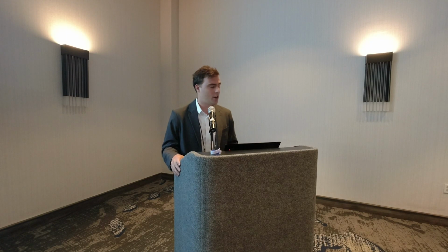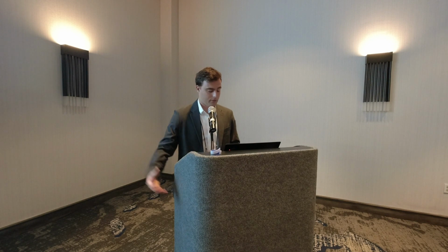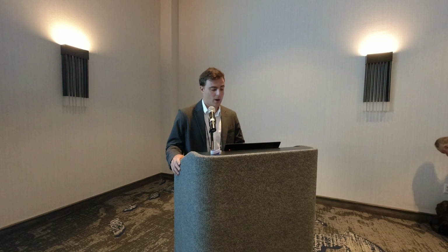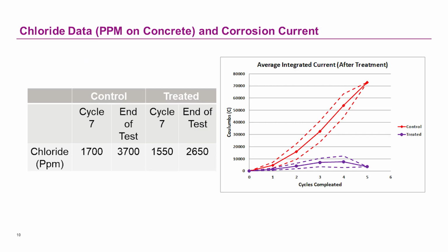And then the test is continued the same way, 2 weeks on, 2 weeks off of the chloride solution, and you continue to measure the chloride data. As you can see on the control, there's nothing stopping the chlorides from penetrating, so they continue to aggressively get higher in concentration towards the rebar. It's not on here, but this depth is at 1.5 inches.